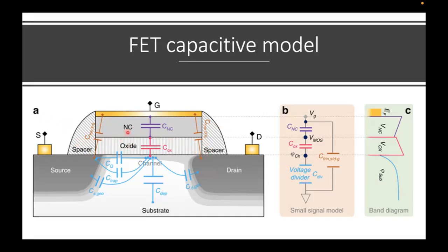Then let's go ahead. Now, this is an N region, with the effect of the positive voltage applied to the gate, which turns, or what we can call inverts, this channel region to be an N type. So this is an N region. And our substrate is a P region because it's an N-channel MOSFET.